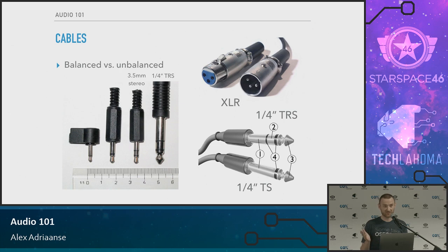You might be wondering, well, who cares? The nice thing is that sometimes cables can act as a big antenna and pick up noisy electronics from around them, such as fluorescent lights. That same interference is going to be on both cables, but because they're being subtracted, it actually cancels out. So that's really nice.